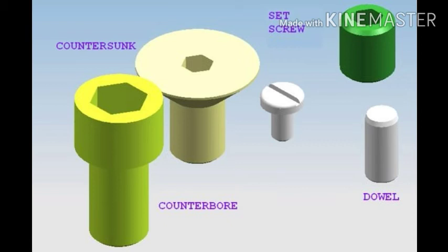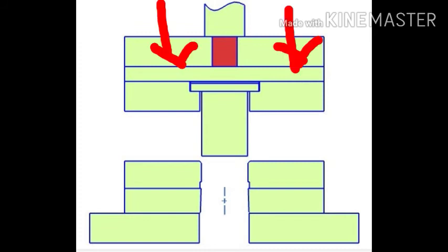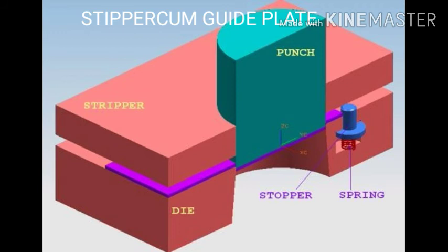The top plate is manufactured out of mild steel or cast iron. This plate should be of sufficient thickness to prevent bending. Because after applying 20 ton of machine force exerted on the tool, at that time there will be chances to bend the top plate due to height. So we have to calculate the thickness of the top plate. We are going to see all its calculation in the next video.